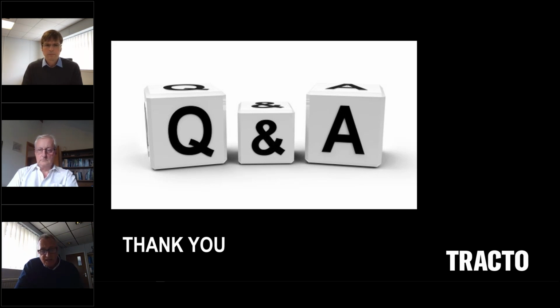But I have to say, and I would stress what Roger mentioned earlier in his presentation, that in all my years of experience in ramming, we've always worked together with our customers, and we've always achieved a fairly high tolerance target. I always guarantee within 1% over the distance. In most cases, it comes much closer than that, and we can ram within inches of our targets. It's always about good setup, a good base support for setting up your Grundoram.